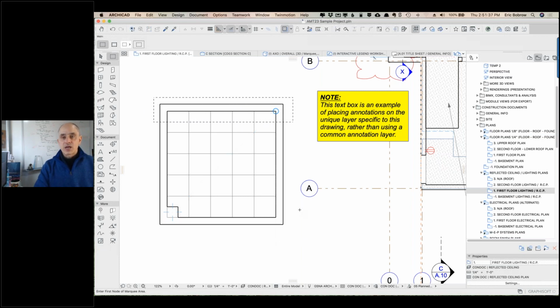So in general, if you want to make something clean and have the freedom of sketching, first of all, sketch on the axis or use the guidelines to make sure that things are square. Secondly, if you don't want to type in a distance at the beginning or while you're just doing a concept design, go back in and pull and grab parts of this as you need to.